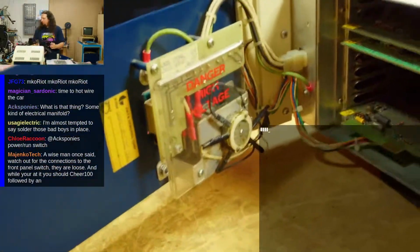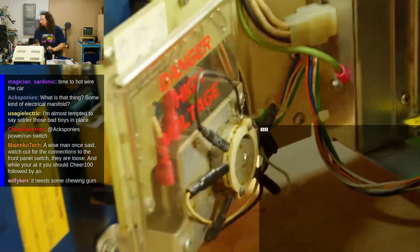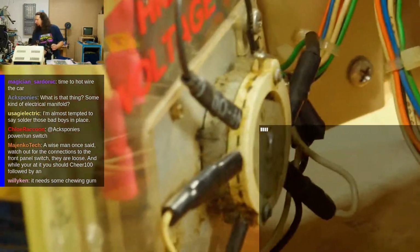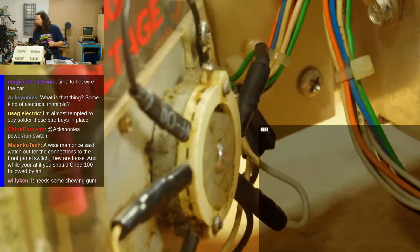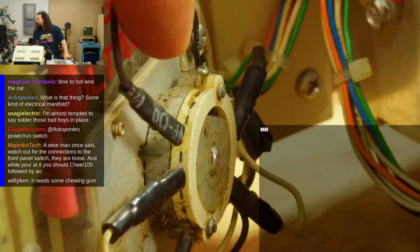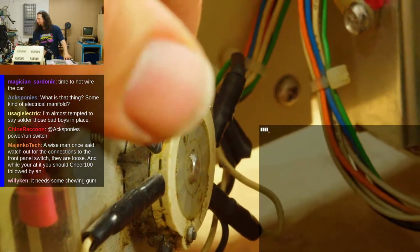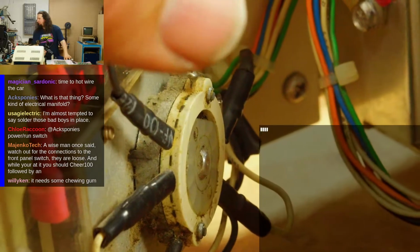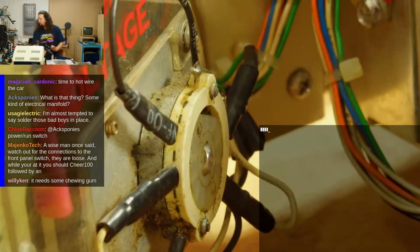I would, except you probably didn't notice this part of this thing. As a wise man once said, watch out for the connections to the front panel switch. They are loose. These look kind of oxidized in here. I really don't like that. Like water or something got into the front panel.